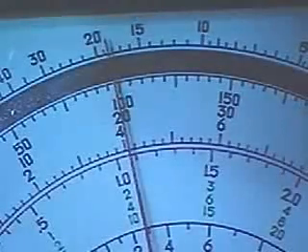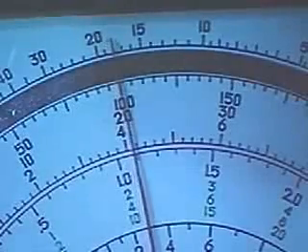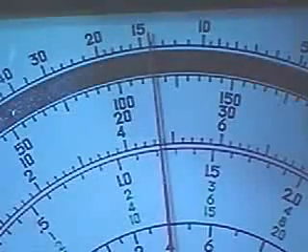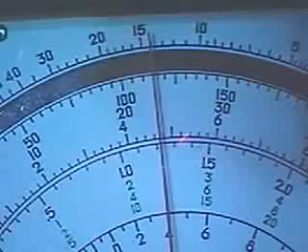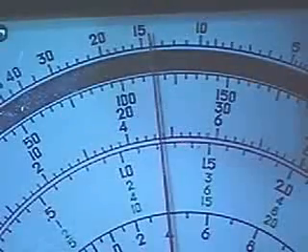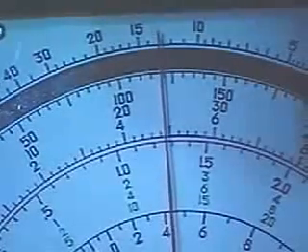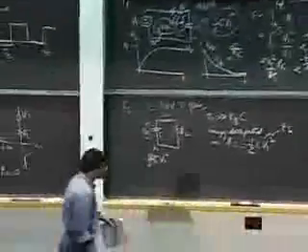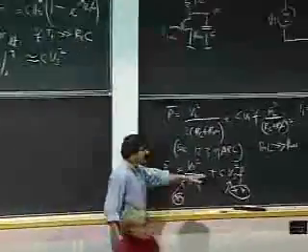Unfortunately, the sampling scope messes up the waveform, so ignore the waveform for now. Just look at the meter as I increase the frequency. Notice that I've increased the frequency by about a factor of 2 or 3, and the needle has moved to the right. I can keep doing that, and the needle keeps moving to the right as I'm consuming more and more power because I'm driving the inverter faster and faster. That should convince you that there is a standby power, and there's some power component related to frequency.